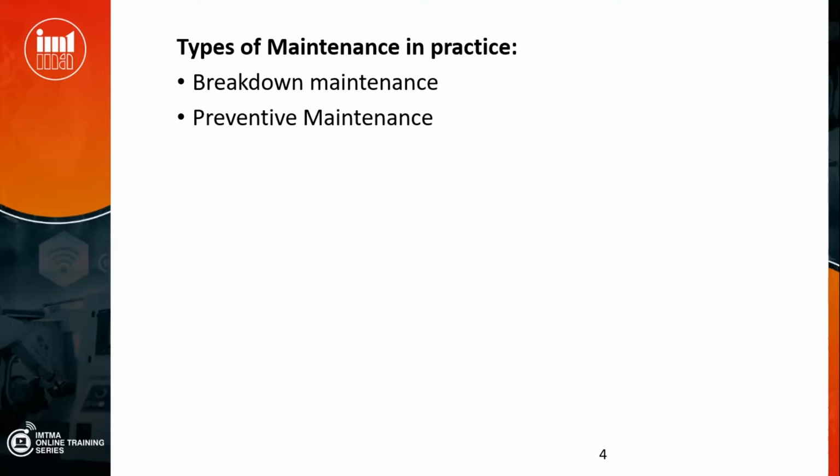Many times with diesel engine operated generator sets, we do preventive maintenance, weekly checks, and there will be only a tick mark. No, you must quantify wherever it is possible. And one step further, you must compare these readings with the previous readings. Or much better is to compare these readings to the ones you got during the installation and commissioning of that particular equipment. That is more ideal.